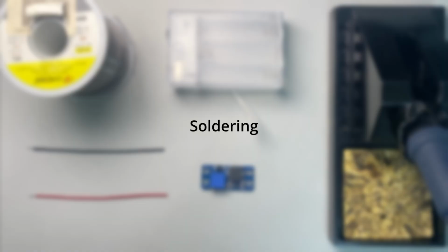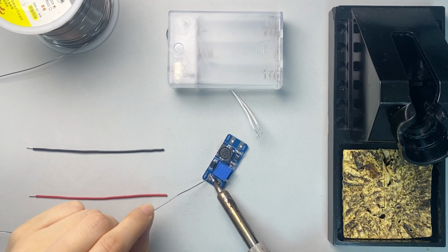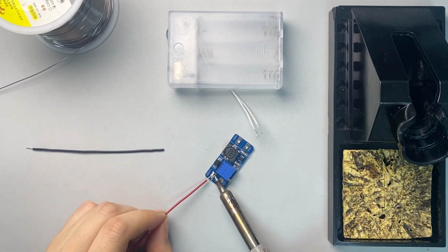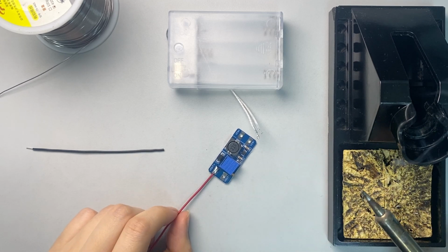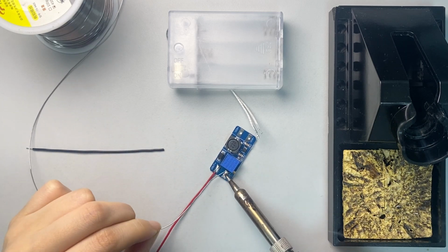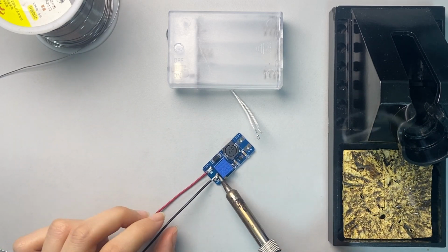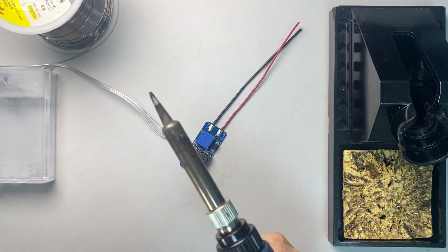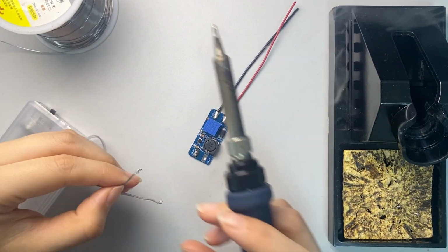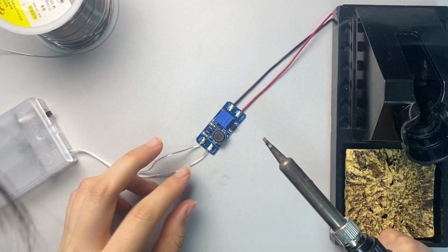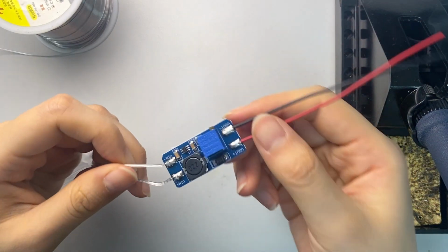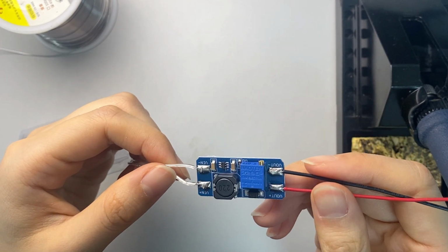To facilitate wiring and subsequent use, we need to solder the wires for the MT3608 module. First, add a little bit of solder to the pads. Then press the wires onto the pads and heat them with a soldering iron so that the solder is fully melted and firmly bonded. Repeat the operation to solder the positive lead of the battery box to in plus, the negative lead to in minus, the red lead to out plus, and the black lead to out minus. Finally, check the solder joints to make sure that the connections are secure and there are no short circuits.